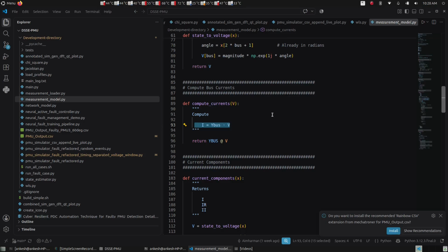The design is simple because we do not have hundreds of PMUs like we have in a real PMU-DSSE-PDC setup. Here, for demonstrating the proof of concept, we are only using 3 waveforms. Though the algorithms which we are implementing on these 3 waveforms are real and they do deliver the results the way they should in a real PMU setup itself. The only part remaining is scaling this setup to a higher order, wherein we have more PMUs, more input data, and a real report generation algorithm will also be needed so that it is properly displayed to the people operating it. But this setup properly gives us a proof of concept about the working of a PMU-DSSE-PDC setup.